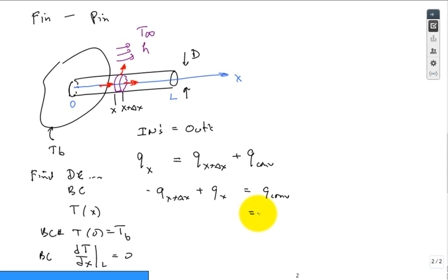All right, probably the convection's the easiest to worry about. So it's just an h A delta T. So it's a convection coefficient. The area, now for the convection, if I blow this up a little bit, it's this area right here that goes all the way around.